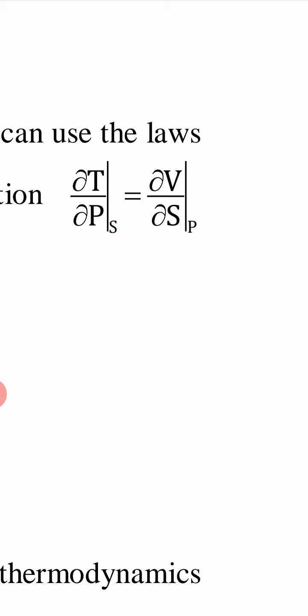These four variables are P, V, T and S. If we write these four variables in alphabetical order, then this order is PSTV. Look at this thermodynamic relation and read in this order PSTV. Then PS is in denominator from left to right and TV is in numerator also from left to right. So write in this order PSTV, PS in denominator, TV in numerator.